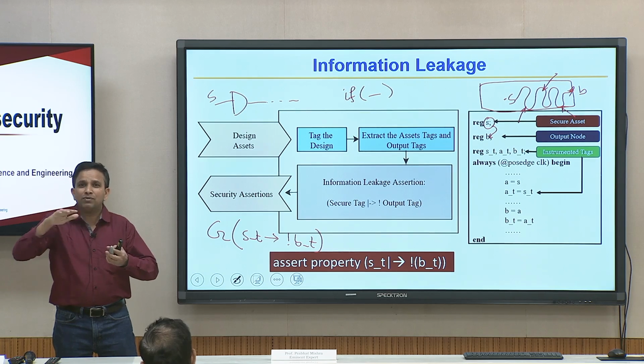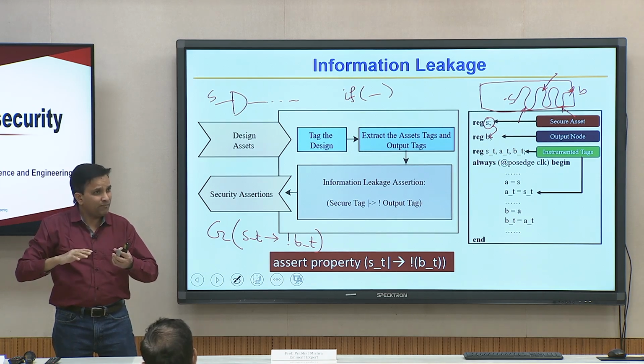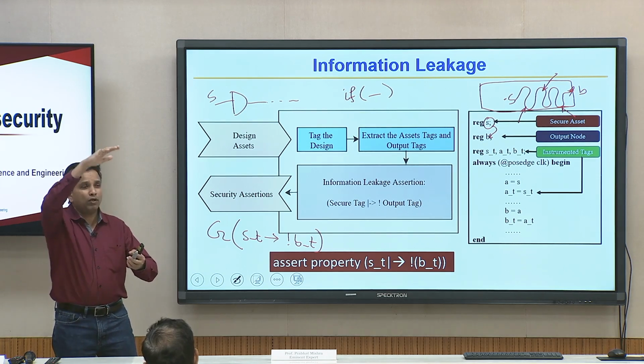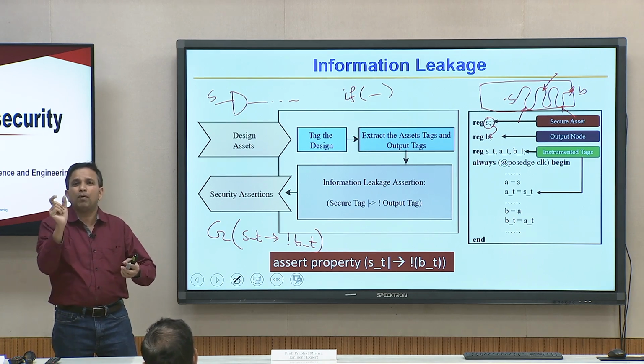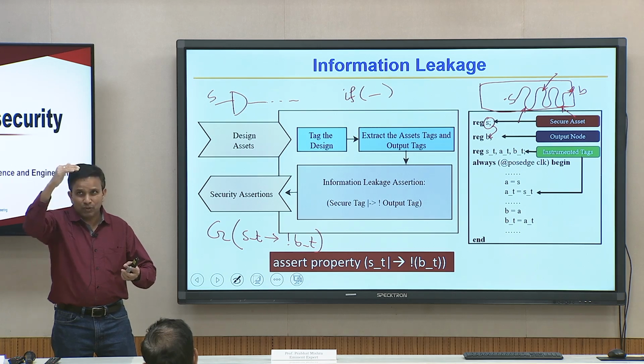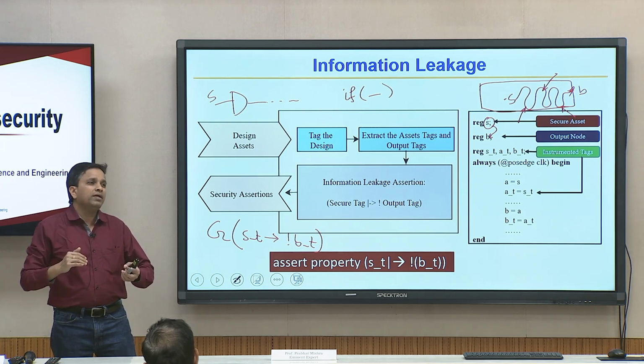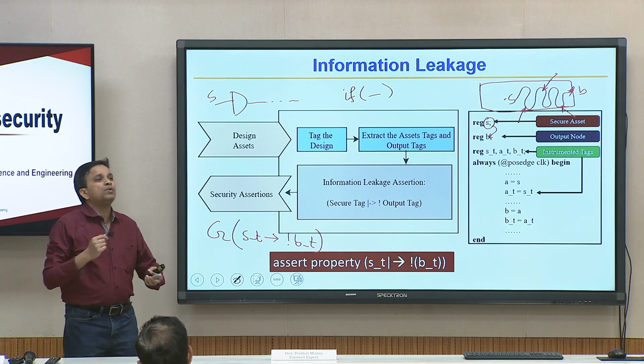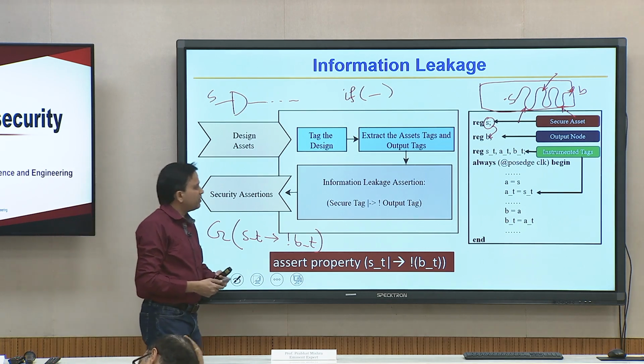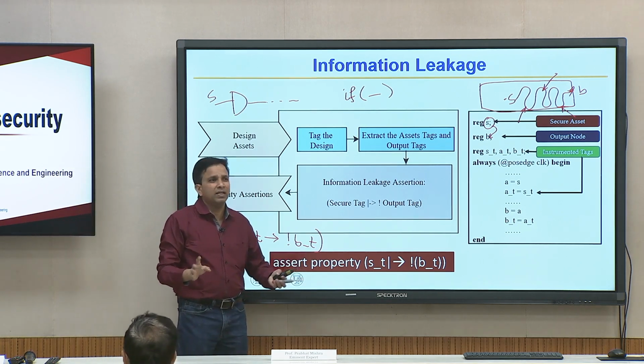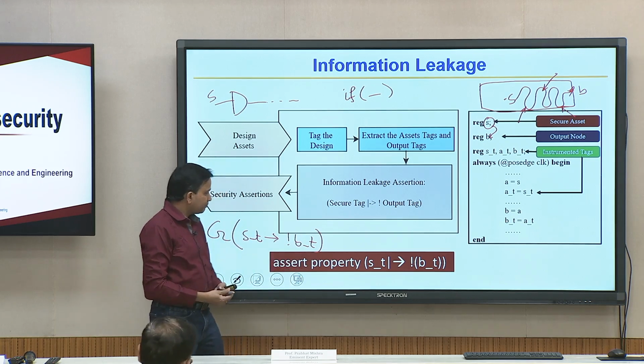The way a compiler gives you lots of warnings or errors, this tool will give you a list of leaky paths with a probability number. The designer will go by the highest probability and slowly go one by one to figure out which one to fix first, or whether it is a reasonable path and there is nothing to fix.